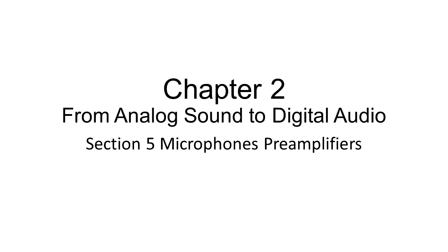The next set of components can be put under the banner of the input section and is optional, depending on the preamp model. Some have these components and more, some have none. The first component in the input is usually a phantom power source for condenser microphones. The next component might be a polarity switch, which will allow you to flip the polarity of the incoming signal.